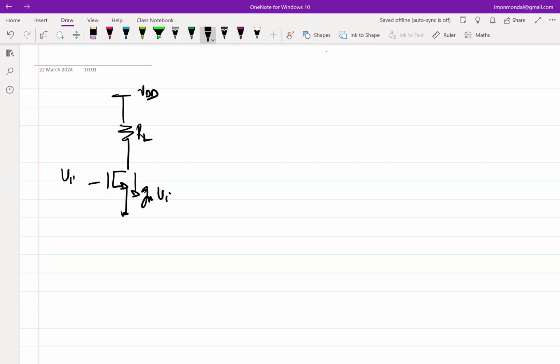So which essentially means that we have to modify the small signal model, and if we modify the small signal model of the MOSFET, an additional resistance or a conductance appears in parallel to the MOSFET. The way I am sketching it, it essentially means that the symbol represents an ideal control source, and the non-ideality is being taken out and put in parallel. That is, the non-ideal GDS is being taken out and put in parallel, just for the sake of clarity.